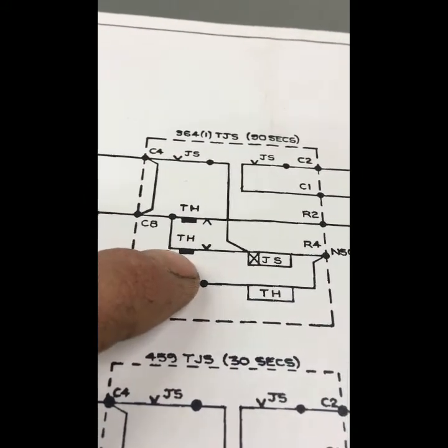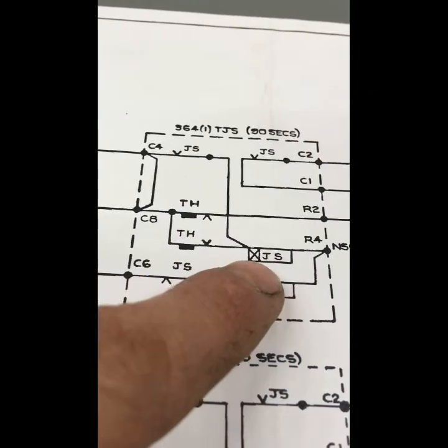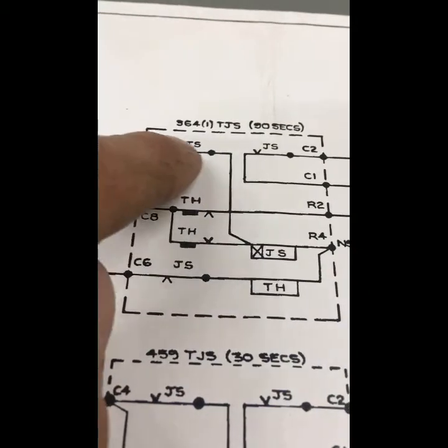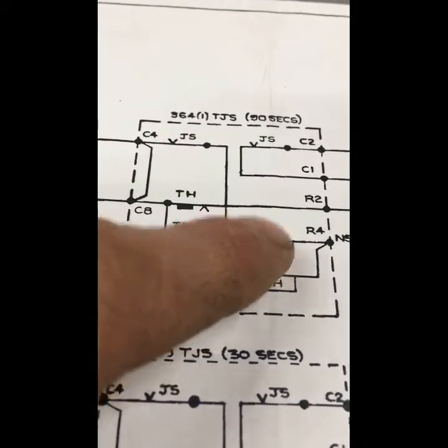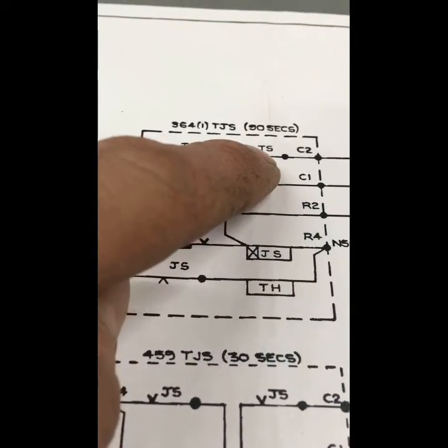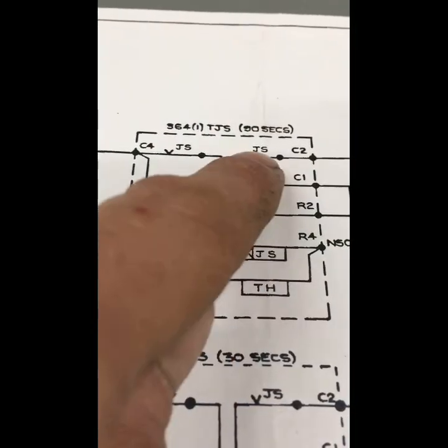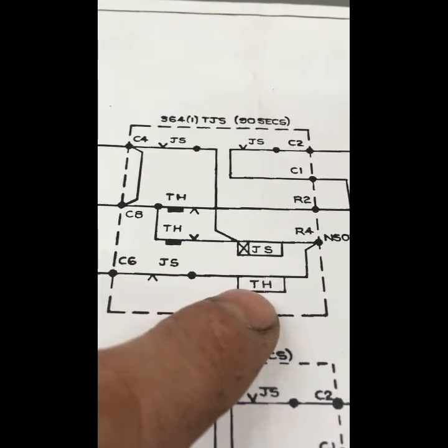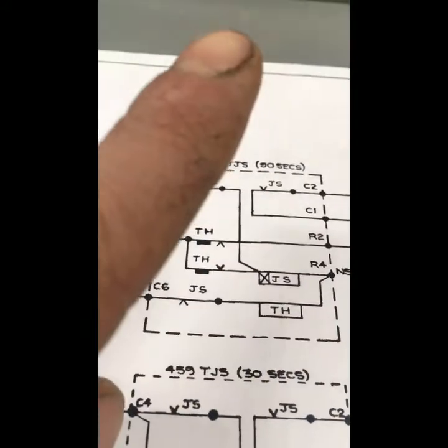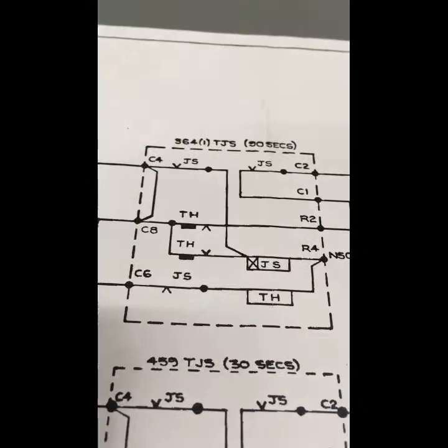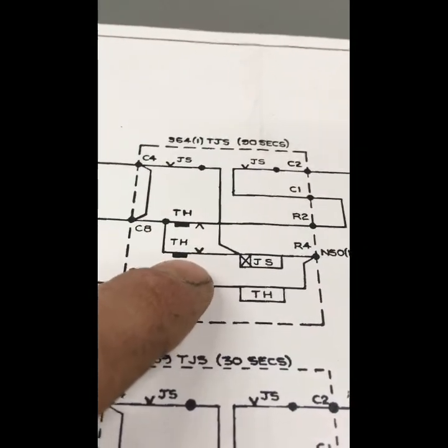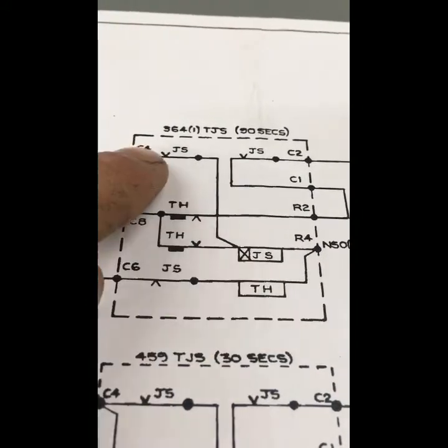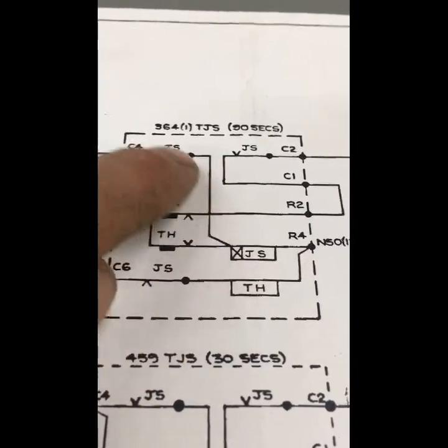So as this contact makes, having timed, the JS picks and sticks, because this is its own contact, so now the voltage can flow down and hold this up. As it holds the JS up, this contact makes, and of course because the JS is now energised and made its front contact, it breaks its back contact. As it breaks its back contact, it takes away the feed to the heating coil. So now the contact starts to cool down and go back again. It now breaks its thermal heating front contact as it's cooling down, but it doesn't matter, it will not kill off the JS because this is held across its front contact there, it's a pick and stick circuit.